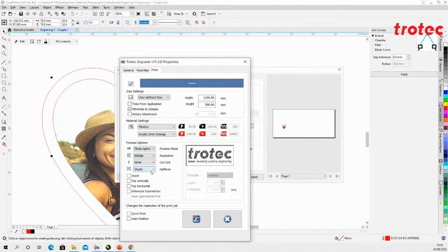And the next thing we need to now choose is the actual pattern itself. So here, the main two ones I use are between these two. So ordered dithering I find gives the most image detail, and the Stucky pattern gives more contrast. So generally I'll try and always work with ordered dithering, but if you're working with a material like wood and you might want a bit more contrast, then I'd recommend also trying one of the others.